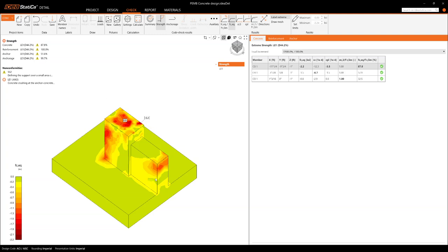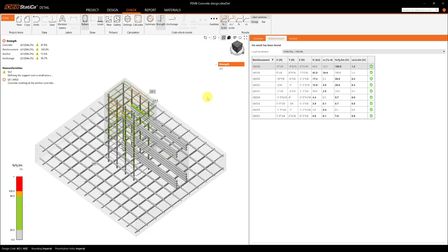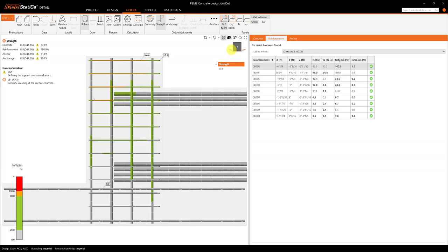So we are seeing now the outside. So these are the stresses on the concrete, the stresses that were calculated, the compressive stresses. And if you click over the reinforcement, then you can see also the utilization ratio, stress versus Fy limit. Fy limit, remember that it's the Fy that you pick for the reinforcement, then multiplied by that factor. And also it can be seen here that that bent bar is not shown there, right?